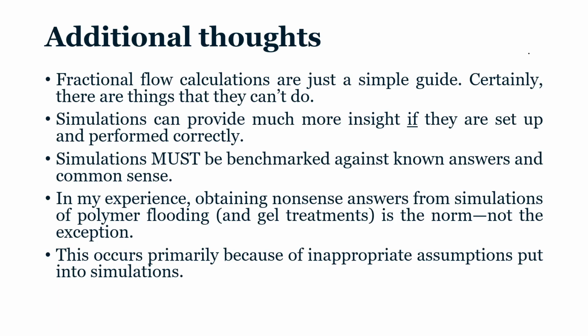You put BHP constraints, but maybe you already have induced fractures. We have seen this in the reservoir response chapter. Some people put the fracture pressure very high, and the pressure during injection was lower, but not changing when they were going from 50 to 100 centipoise. So maybe the frac pressure was wrong. So once again, be confident about your data, go back and check, do some extra tests, because this will be really key to get your injectivity, economics, and business case right.